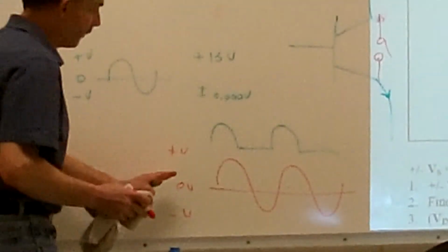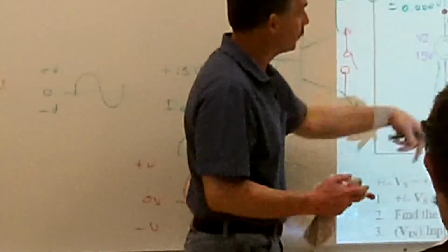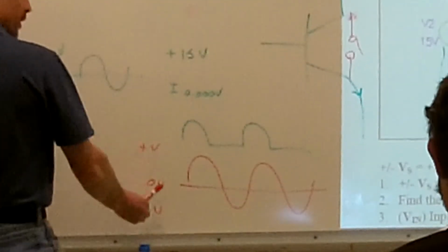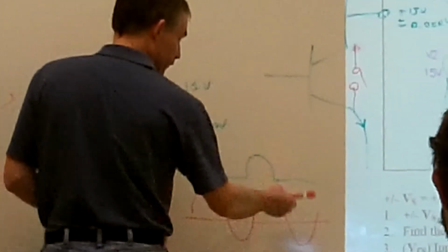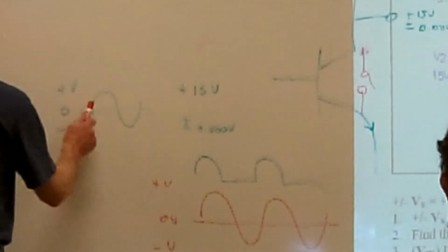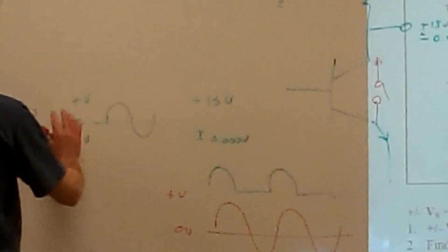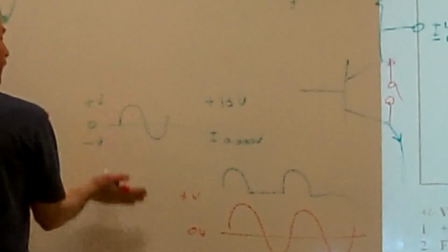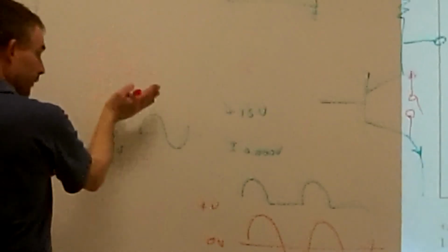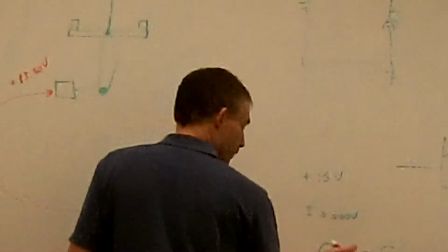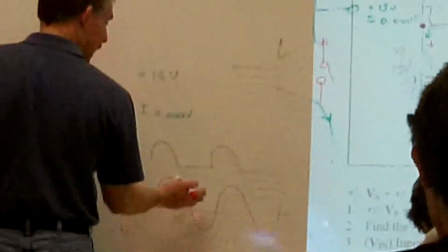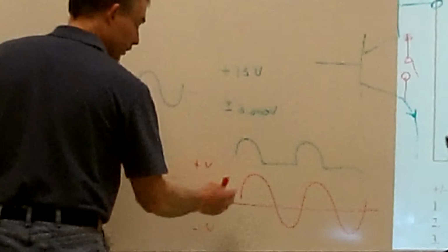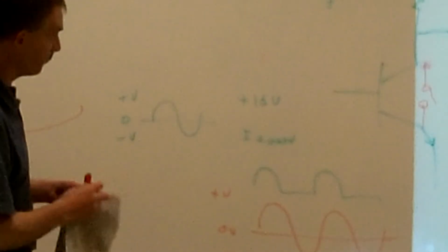So that's another benefit of an op amp. I don't have to build up a whole bunch of voltage dividers or anything like that. And since I have dual power supplies in there, my output signal can go positive, negative. I don't have to do anything. I don't have to elevate my input AC signal up onto a DC offset. I don't have to do that with my DC output, or my offset of my output either. I don't have to have that on the output. It'll automatically just swing positive and negative.